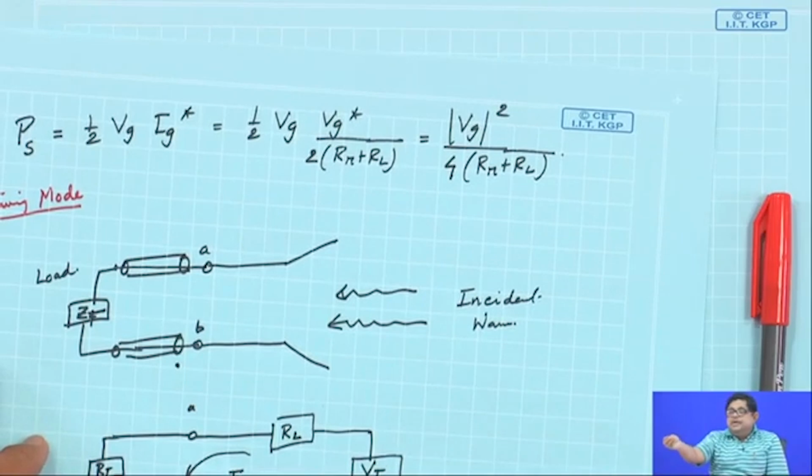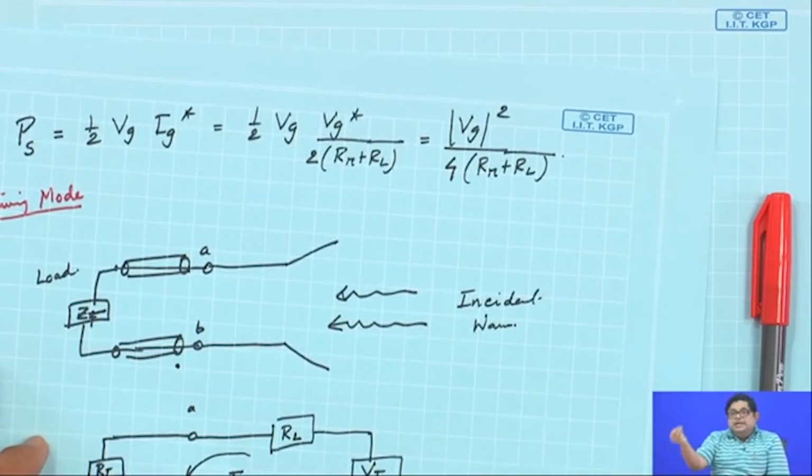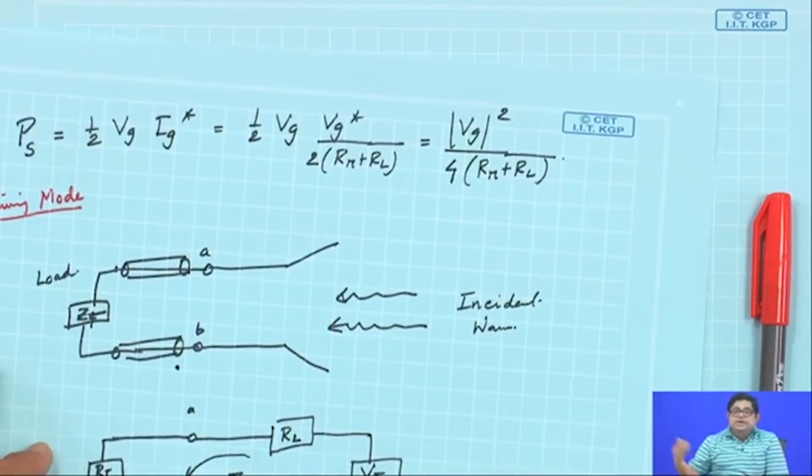That electromagnetic field will go there, then there will be some secondary currents induced in those bodies, and that will again radiate and come back here. The net effect of that is a mutual coupling, so a mutual impedance. That means the input impedance, whatever we have discussed here, was the total effect, that means self impedance plus mutual impedance. So, that mutual impedance will get affected the moment I have a nearby thing.